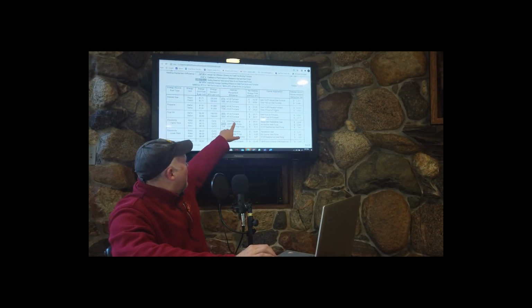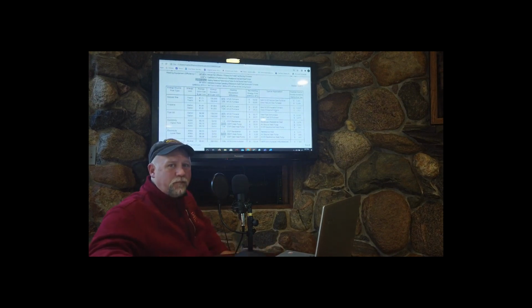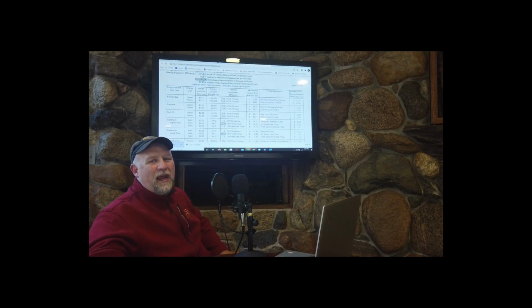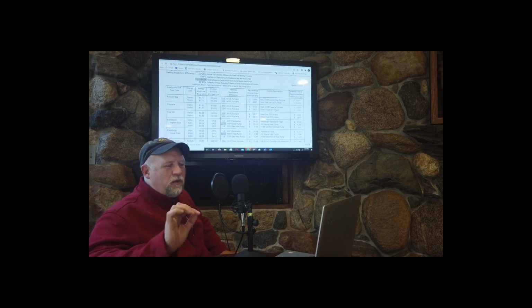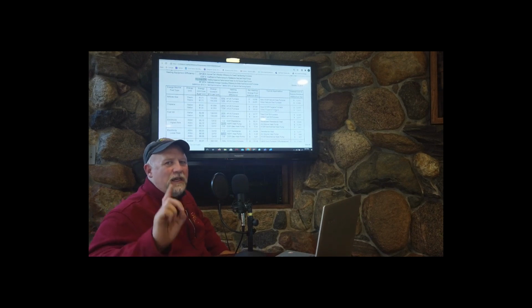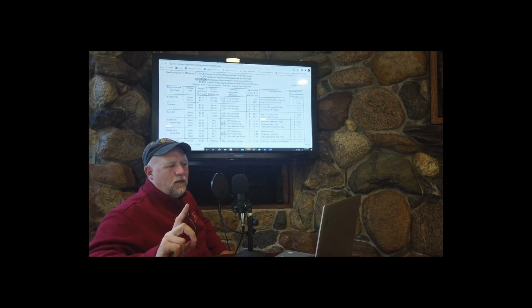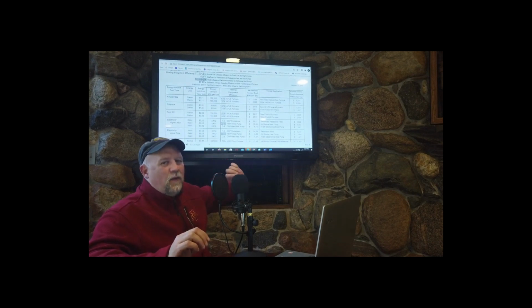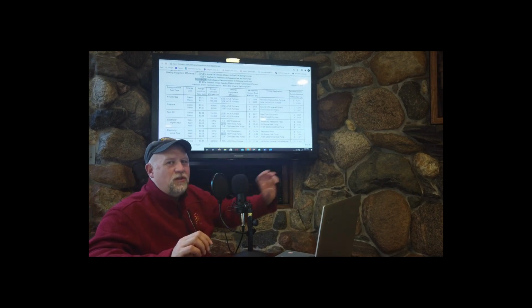And for an electric resistance heater, all of the heat is turned into friction, and all of that friction is dissipated by the air within the room itself. So the coefficient of performance for a resistance heater is 1. 1 kilowatt of electricity consumed, 1 kilowatt of heat put into the room.